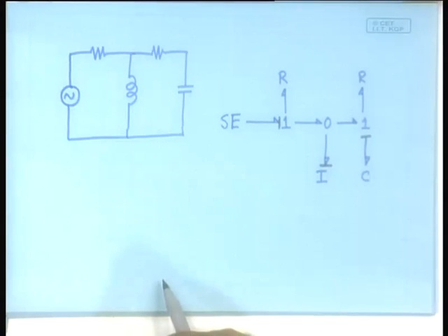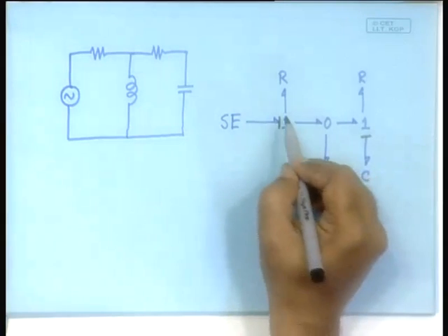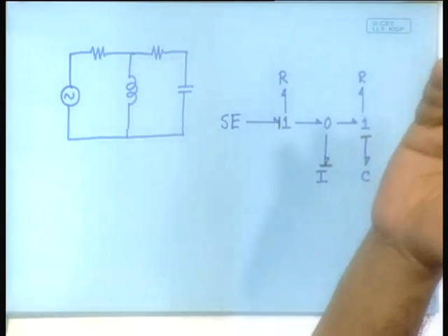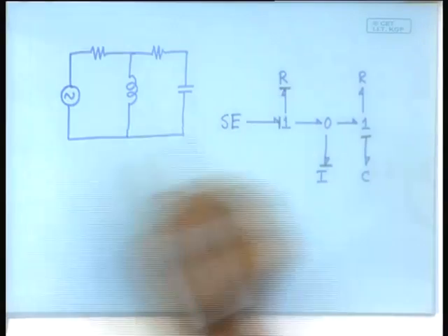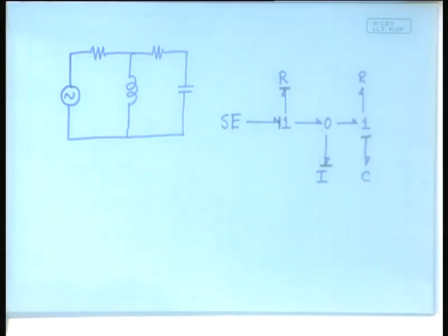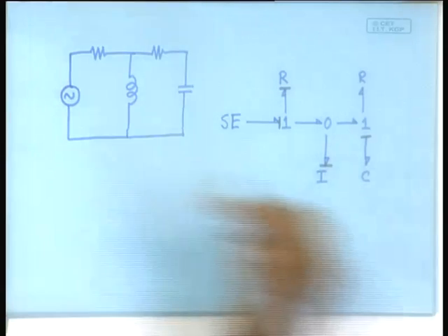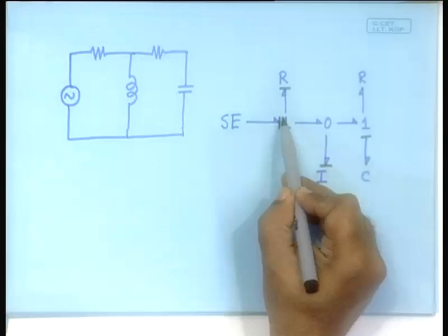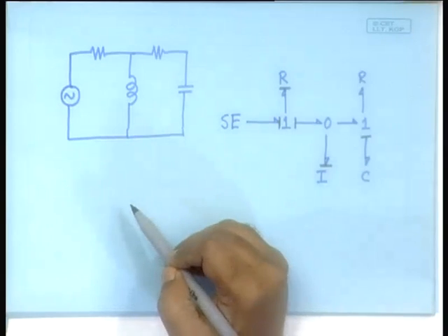How will you complete it? In order to complete it, you might argue, okay, what is the problem? The problem is that this one junction does not yet know where the effort information is coming from. Let it come from here. Suppose, what does it mean? It will immediately make this one complete, because this has to take out the flow information.